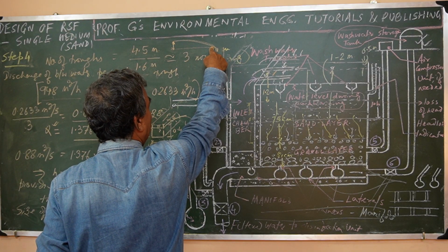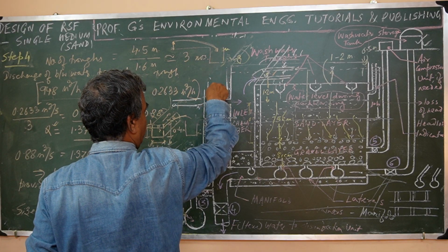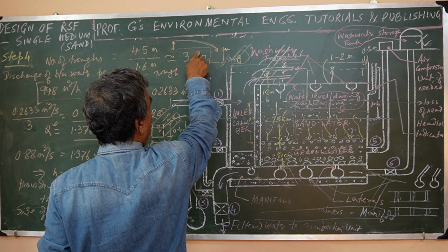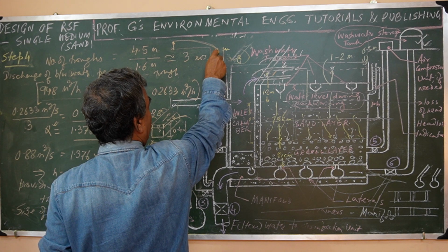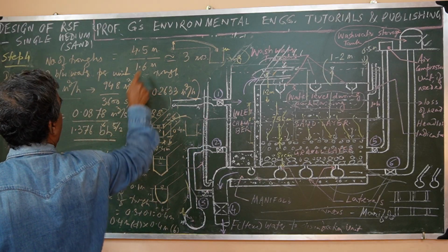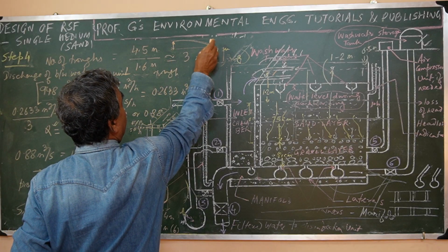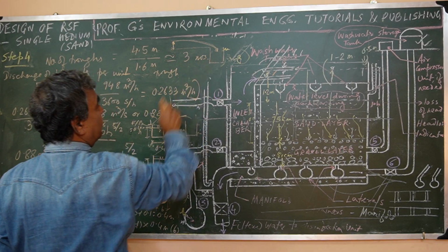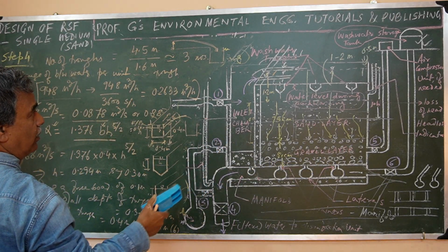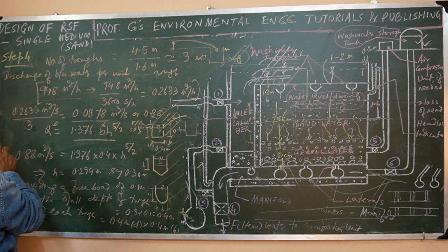So it will fall through critical depth, free falling, a rectangular channel with the flow, which is freely falling into the gullet. So that would be the depth here at the uppermost point, and that depth we will consider throughout. We cannot reduce this, because structurally it will be difficult to change the depth of the trough as it goes towards the gullet. So I think it is clear to all of you.